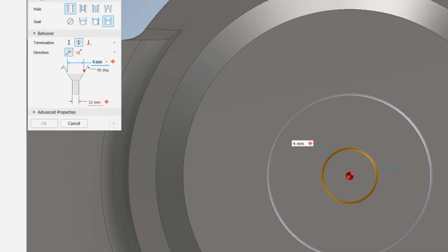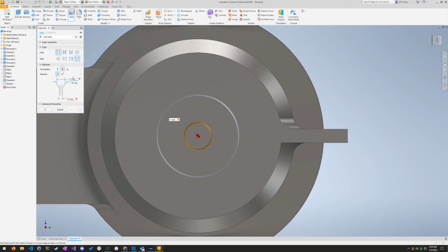hole is, right? I'm not going to talk about why it is on a gun, but usually we use countersunk holes for screws, because the head of the screw is wider than the rest of the screw, of course. And we countersink it so that the screw head doesn't sit above the wood or the metal. When you rub your fingers across the surface, the head of that screw is under the surface, so it doesn't catch on stuff, right? So when they say countersink diameter, I'm talking about the widest part there.